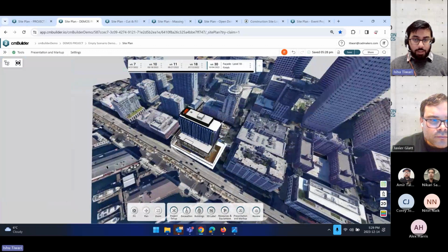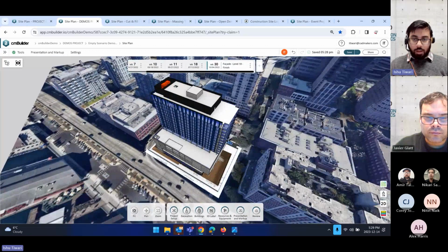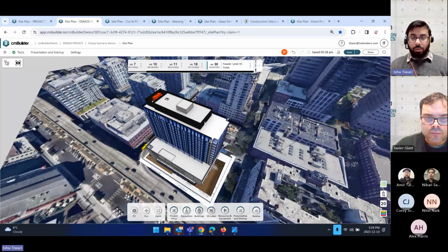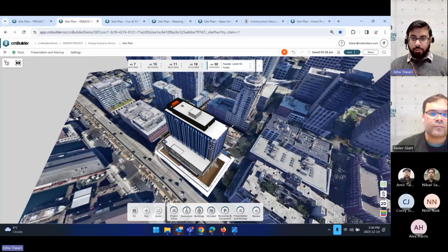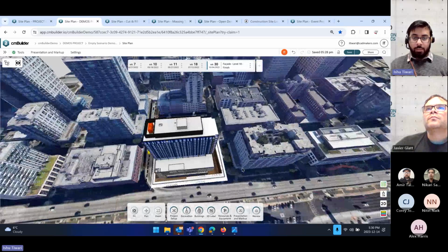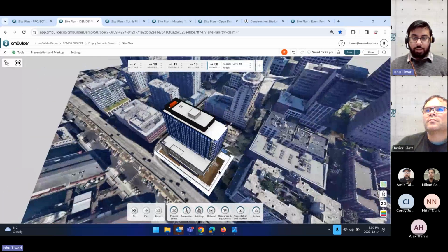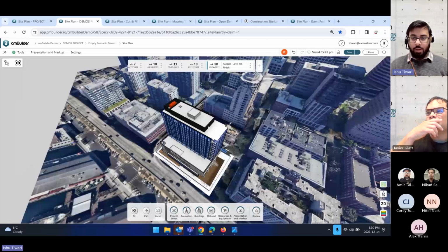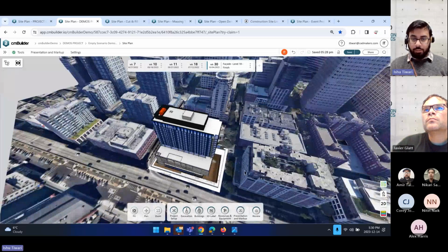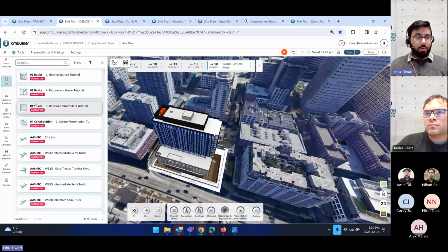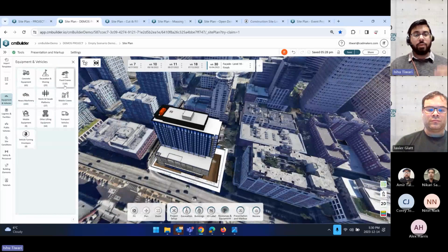Yeah. The final part is where I want to show the crane planning. When you're working with the cranes, I like to have the full building in view, and at the same time the surrounding area, which is much better so I can see if there's any intersection or encroaching on any of the neighboring buildings. So I can look up the kind of crane I want to use. We have a lot of fixed cranes, 110 total, actually it was 108 yesterday, so we just added two in a day.